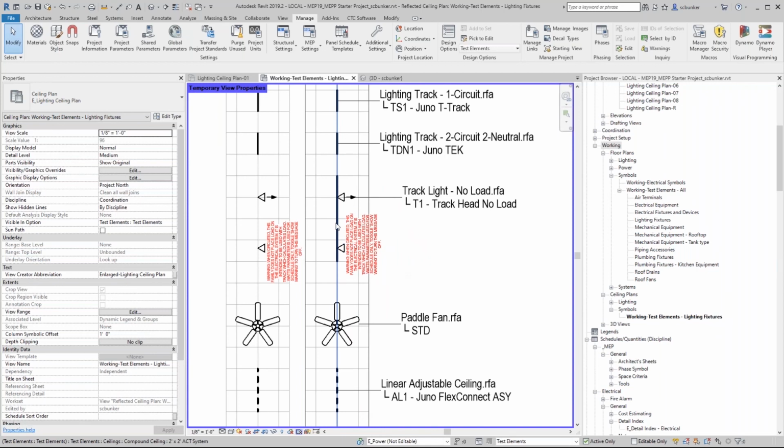We have a method of doing track lighting in the project, and the track light will calculate according to the requirements of the NEC. So in the NEC, track lighting load is calculated based on the length of the track, not based on the number of heads attached to it. As I'm sure you know, it's the length of the track, or you can put a current limiter on it, and it's the rating or setting of the current limiter. So we have a method of doing that in the pack that I've not seen in Revit otherwise.